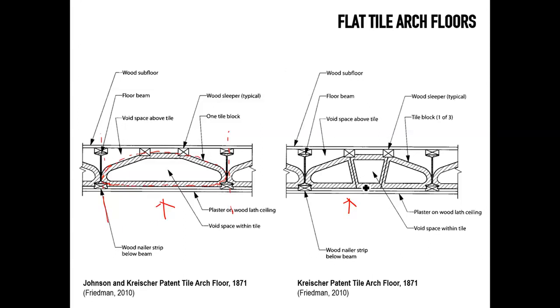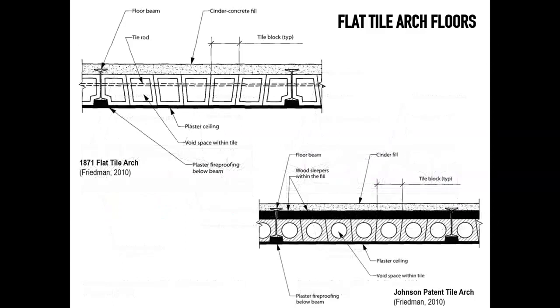So in this case here, you have a central piece that is pushing down, but because it's trapezoidal, it is transferring some of these lateral forces onto these almost triangular pieces that eventually transfer back onto the beams on the side. Now, this is the basic principle, the flat arch of terracotta or clay tiles. And the system was obviously developed further, almost in the same period, very quickly, once it was realized that there was a need to have a more practical approach. So instead of having larger pieces all put together, suddenly these blocks became smaller and smaller.